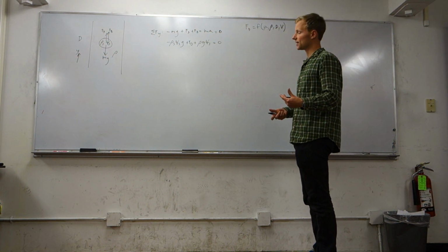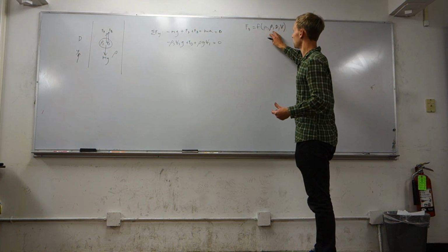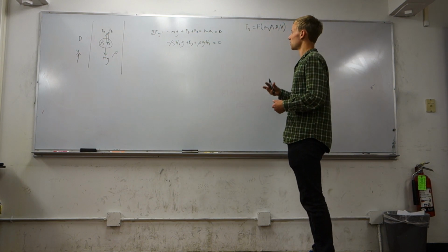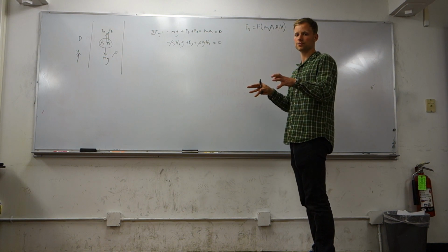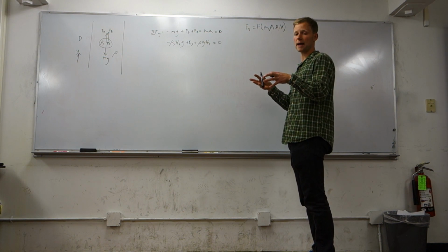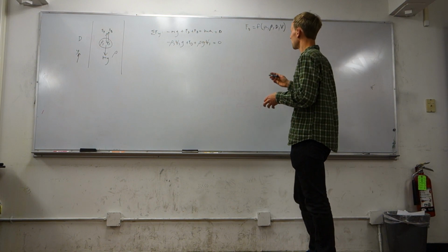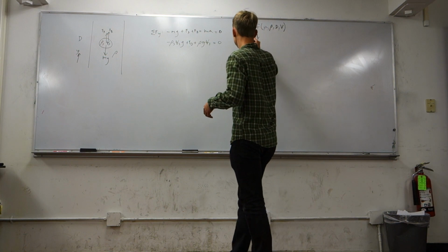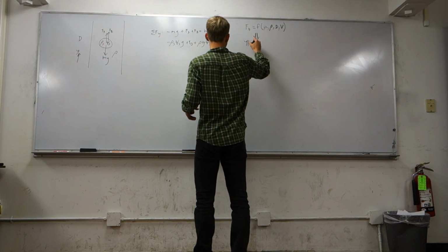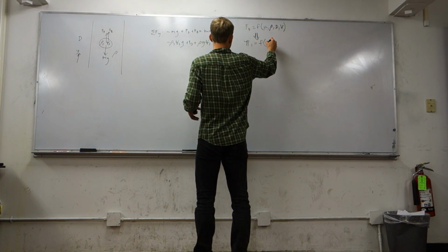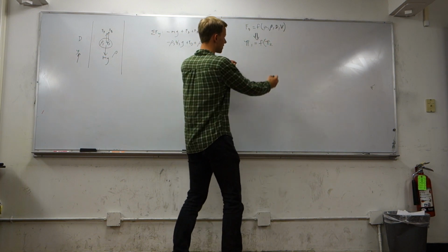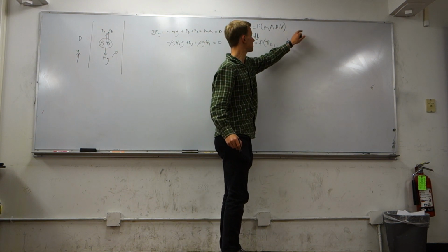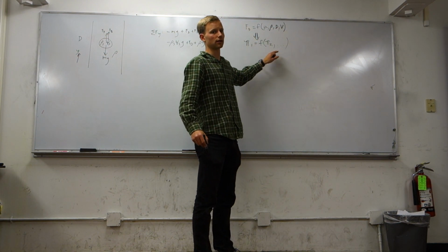And there's a better way of doing this, which is to collapse these variables into non-dimensional numbers or groups, and then use the relationships between non-dimensional groups to get back out what the relationship is. So what we can do is convert this into a function of two pi groups. So we'll have some pi1 is a function of some other pi group. And in general, there could be other pi groups in here. If we added more variables that we think our problem depends upon, there's going to be more pi groups that are going to be related.